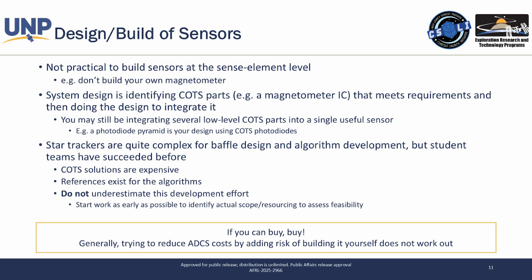Fine sun sensors are usually better tuned. You know the characteristics of those photodiodes much better. There's going to be quite a bit more estimation behind where they think the bright object is. You might use several in combination to get a real vector for the sun. Those are usually accurate to 5 to 10 degrees, maybe a little better. They may state they're a bit better than that. That's kind of the difference. So yeah, you totally can use fine sun sensors.